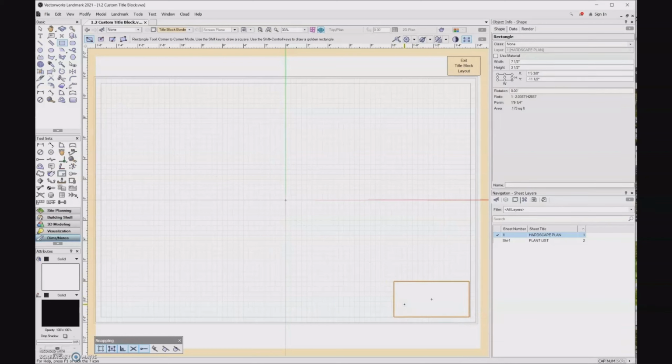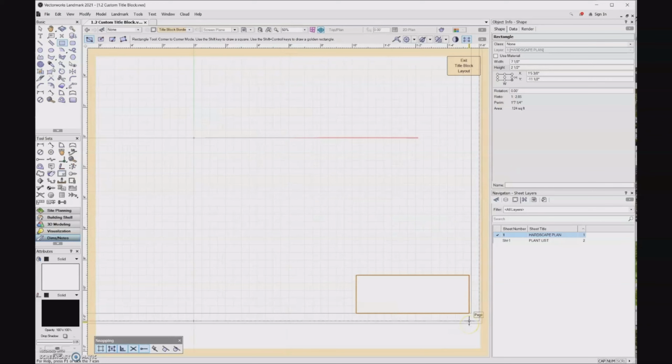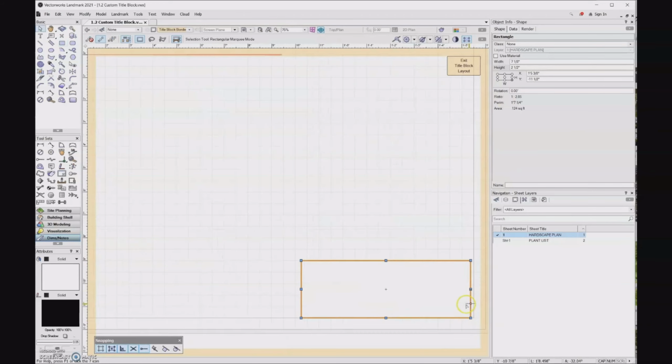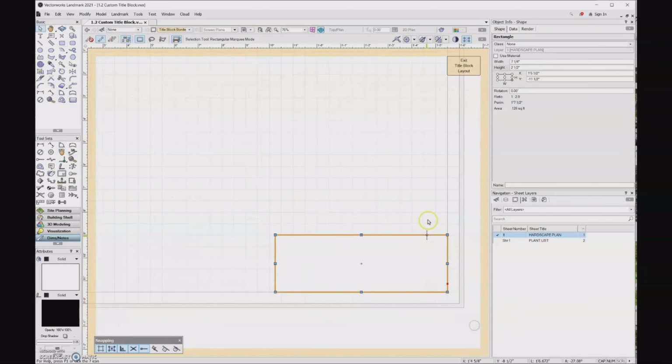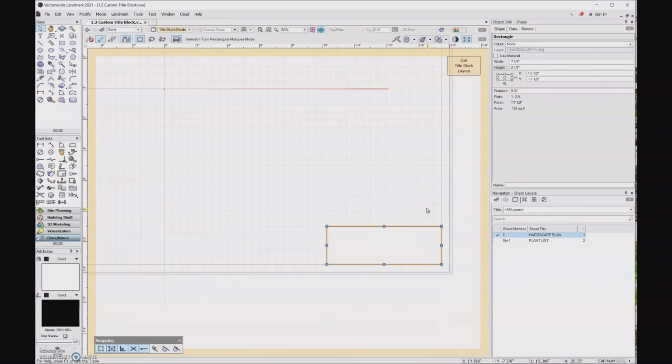And it's a good thing to keep in mind how much space you want your title block border to take up in your file. Make sure that it's not too big, as well as be mindful that it's not too small. So what I would recommend is for your height, keep your height somewhere in between 2 inches or 3 inches. So I'm going to start out around 2.5 inches, but I have a little bit of room to play around with that if I'd like to see something different. So I'm just going to come up with a series of boxes and text. I'm going to go ahead and pause the recording for now, and then come back once I have my design ready.